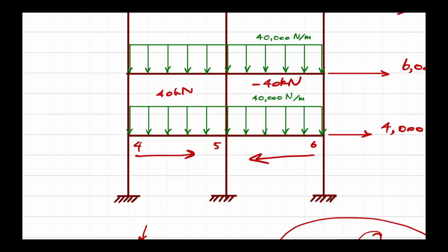If the graphic user interface allows you to do global coordinate loads and local coordinate loads differently, okay, for the global one, you just follow the direction of X, the direction of Y, positive, negative, how the load aligns with these axes. But if you apply it in local coordinates, then how it starts and where it ends does matter, in the computer's perception of your load. You can do this and just put 40 and plus 40 for the different setups of starting and ending node, for a different setup of the local coordinate, and you will see the different solution.